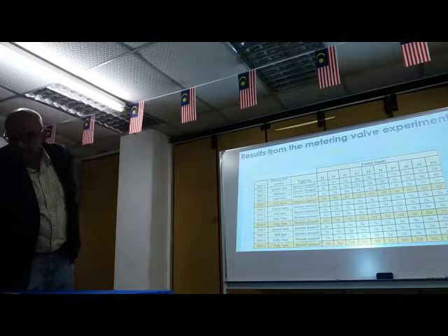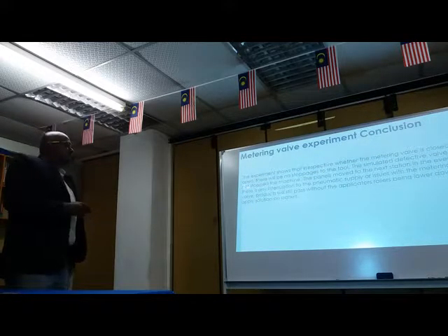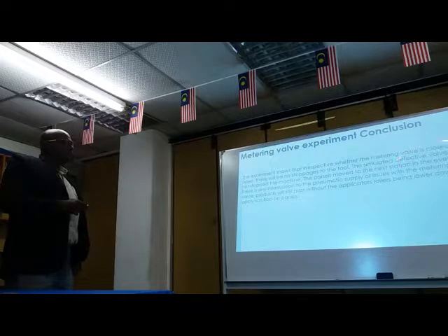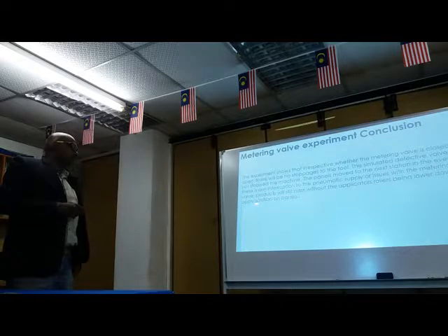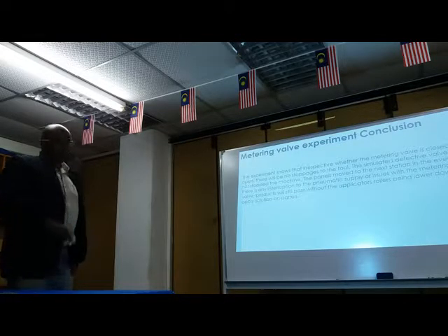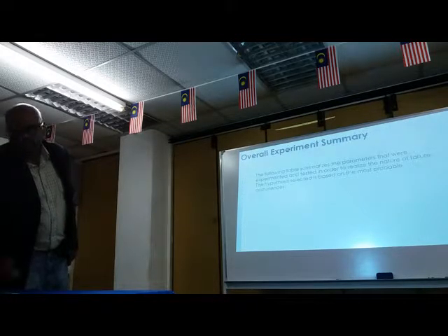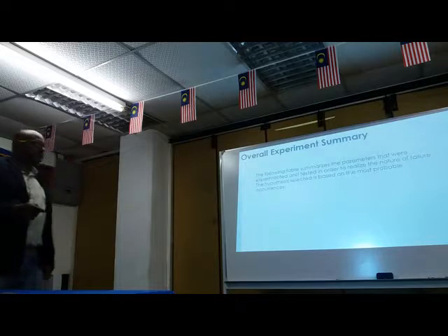So how do we conclude this experiment? This experiment shows that irrespective of whether the metering valve was closed or open, there will be no stoppages to the tool. The simulated defective valve did not stop the machine. The panels move on to the next station. In the event there is any interruption to the pneumatic supply or issues with the metering valve, the products will still pass without the applicator rollers being lowered down to apply solution on the panels. So with that, we conclude the metering valve can be a culprit as well for this issue.